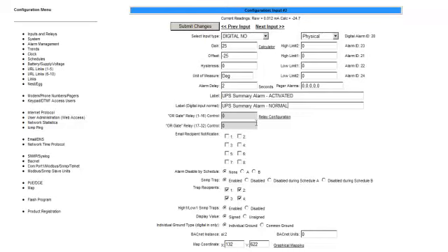A relay could also be assigned for an output, email notification, alarm disabled by schedule, SNMP, and then the graphical map are other points that can be configured. We're going to click on Submit Changes once everything's done. This input is an example of channels 1 through 8 that are being utilized. At the top, we can see a raw and a calculated to show if it was in or out of alarm.